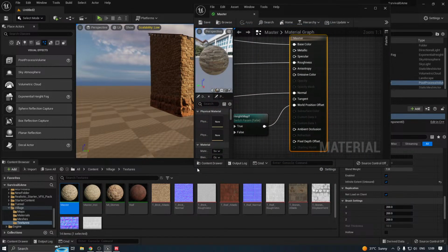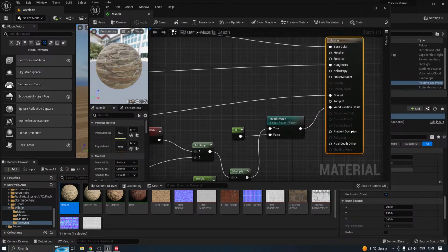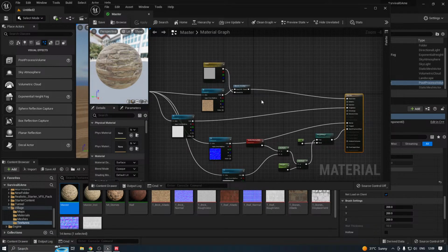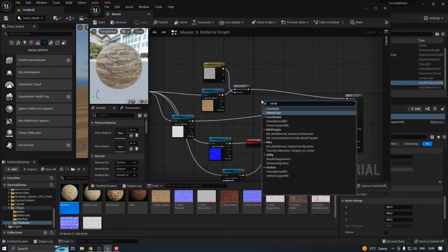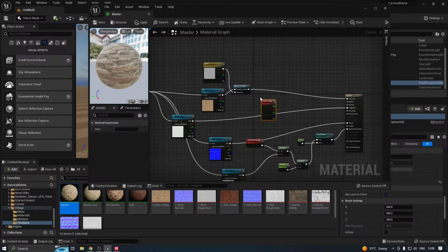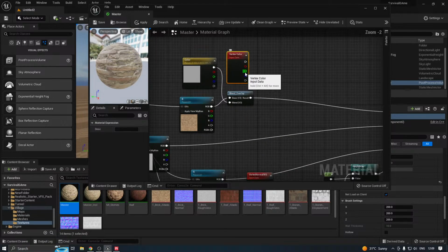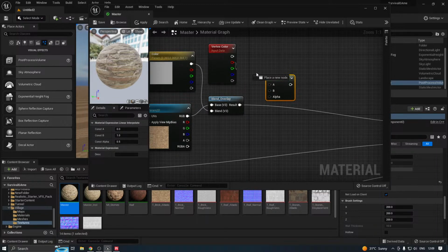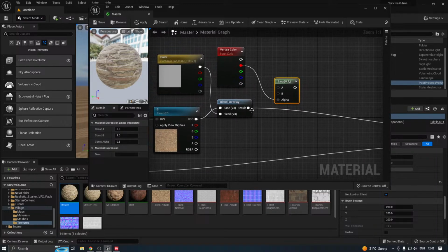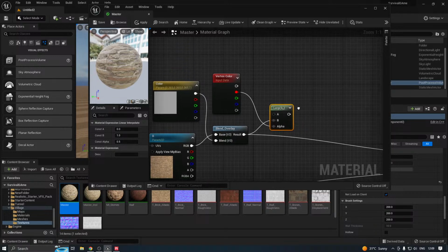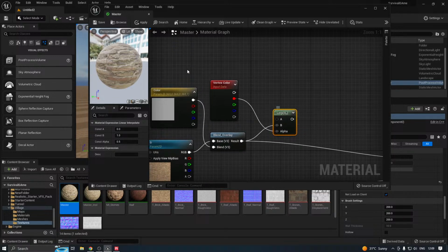So I'm gonna open the master material. Okay, search for text color and hold on L and left click for this slurp. I'm gonna connect this red channel to alpha. This result goes to B and we need a different variation, different color for this text.